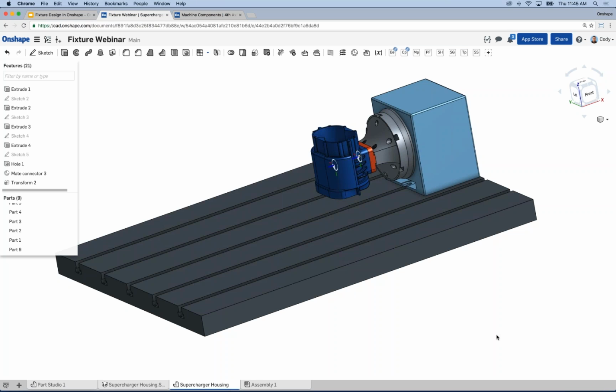You're bringing in a part. I would recommend, and this is just a recommended approach, put all your library parts in a single document: a vise, table, fourth axis, clamps, whatever it is that you're designing, and then just insert those parts into whatever new projects you get. So if I get a new project tomorrow, I'm going to walk through the same workflow: import it, bring in my vise, my table, whatever it may be, model the necessary pieces I need to model, and test the motion out if I need to. So that's really the workflow from start to finish.